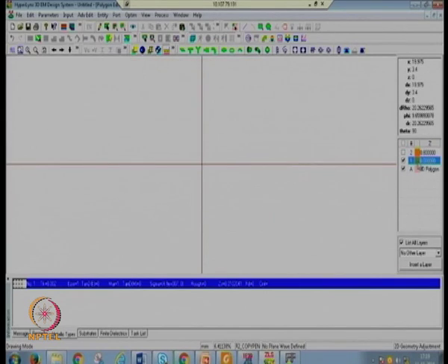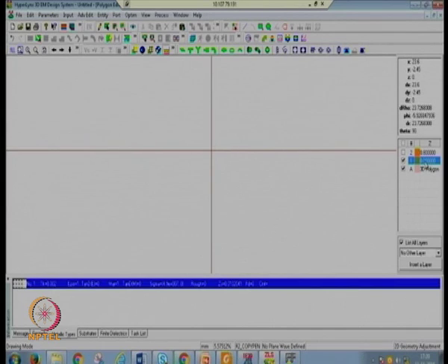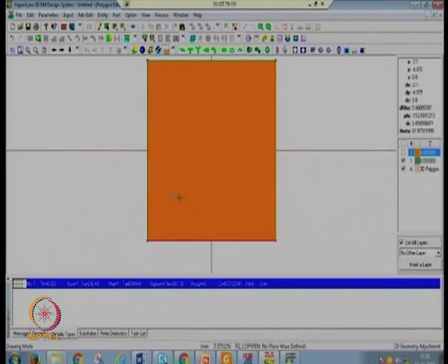If you see here in this window, in green there is a dotted line. So this dotted line shows that it has infinite conductivity and it is a ground plane. Now if you design anything on this particular layer, then it will be like you are cutting a slot on an infinite ground plane, because by default it is an infinite ground plane with infinite length and infinite width. So if you are designing anything above that, it is equivalent to cutting a particular slot in that plane. So this is my rectangular MSA.